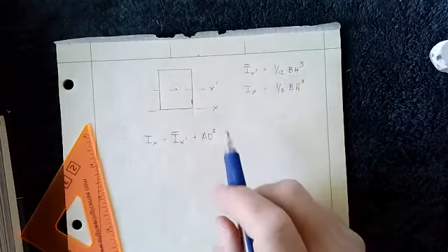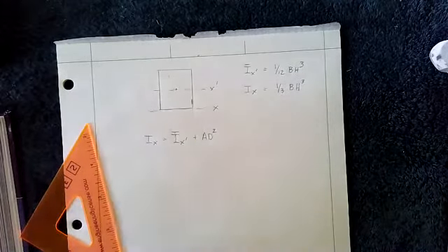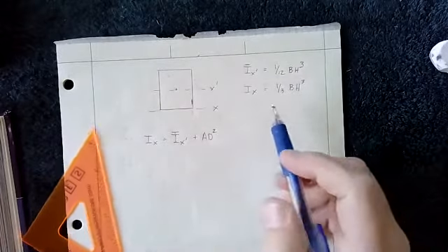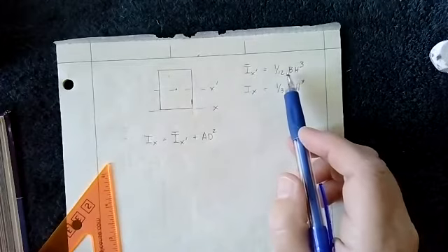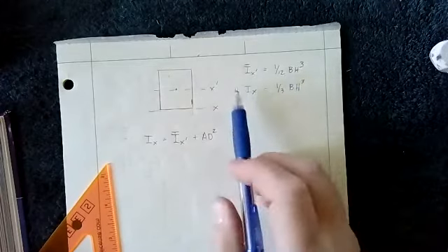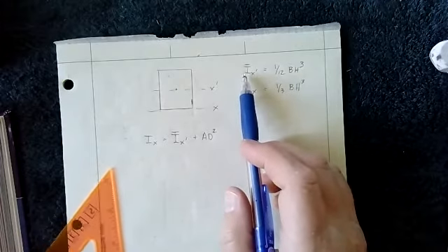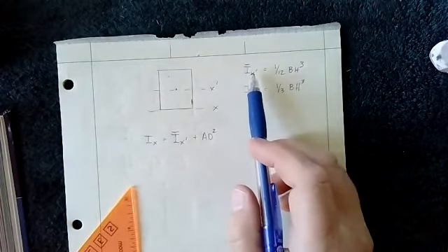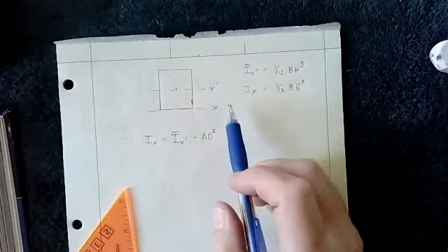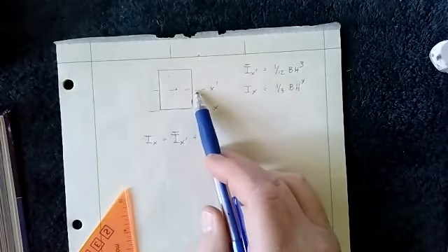Most of the time, when you look on a table like the one in your book, which is on, I think, page 500, 501, the moment of inertia is usually referenced by the centroid. The reason for that is that if you want the moment of inertia in a calculation, very rarely are you going to be using a single shape, or know that the axis of rotation is necessarily right at the centroid.